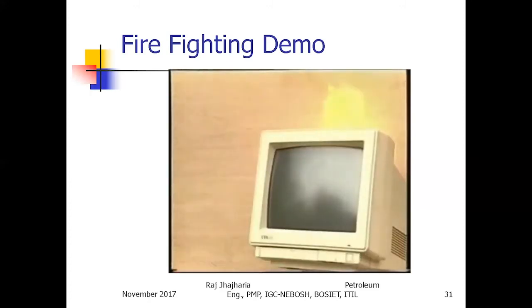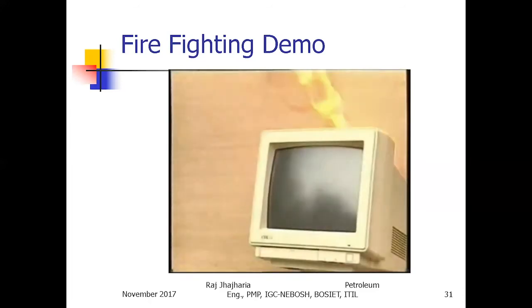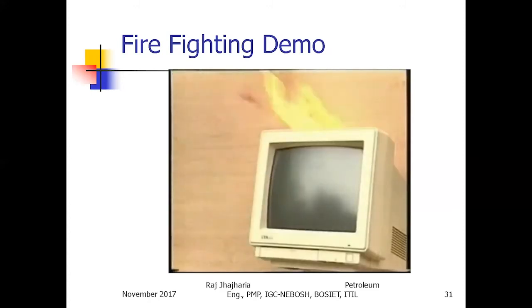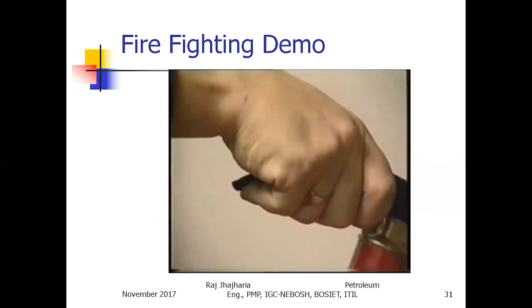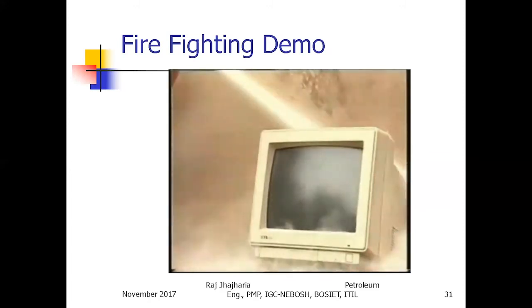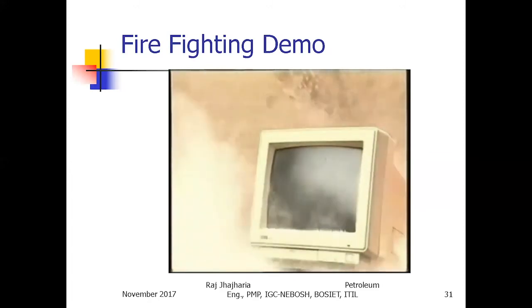When confronted with a fire on electrical apparatus like this, whenever possible, switch off and unplug. Most of the electrical equipment you'll come across will be enclosed in some sort of casing, which the powder will not readily penetrate. So it's necessary to get as close to the fire as you can, without putting yourself in danger. Then the powder is more likely to penetrate the casing.